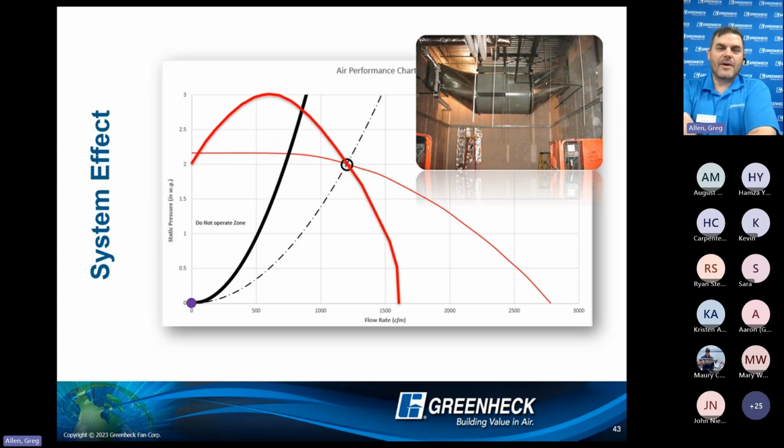Now, remember, fan curves offset parallel. If I speed that fan curve up, it maintains its shape, but I had to speed it up quite a bit. So in this scenario, I have a not opportune installation, right?